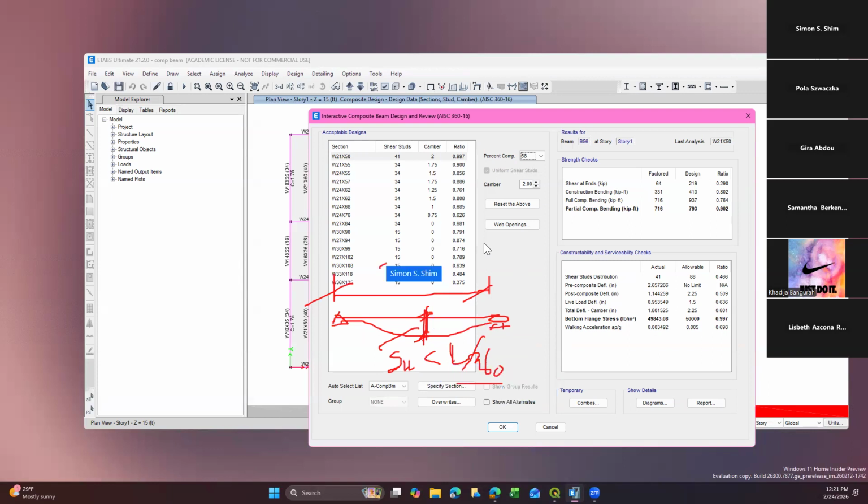If you have a span of, let's say, 45 feet, then 45 feet times 12 divided by 360 gives the maximum criterion of 1.5 inches. So here you see the allowable maximum. This is one straightforward example: the live load deflection criterion, length divided by 360, should be met.